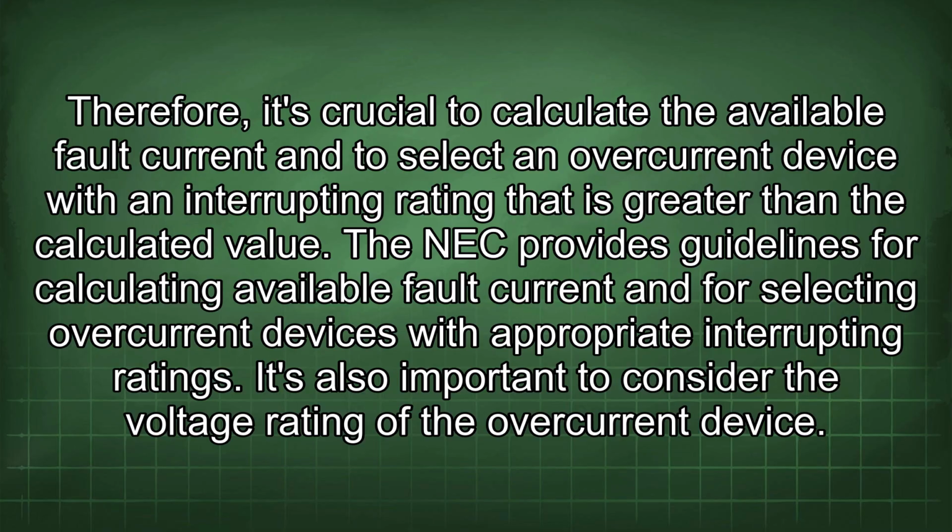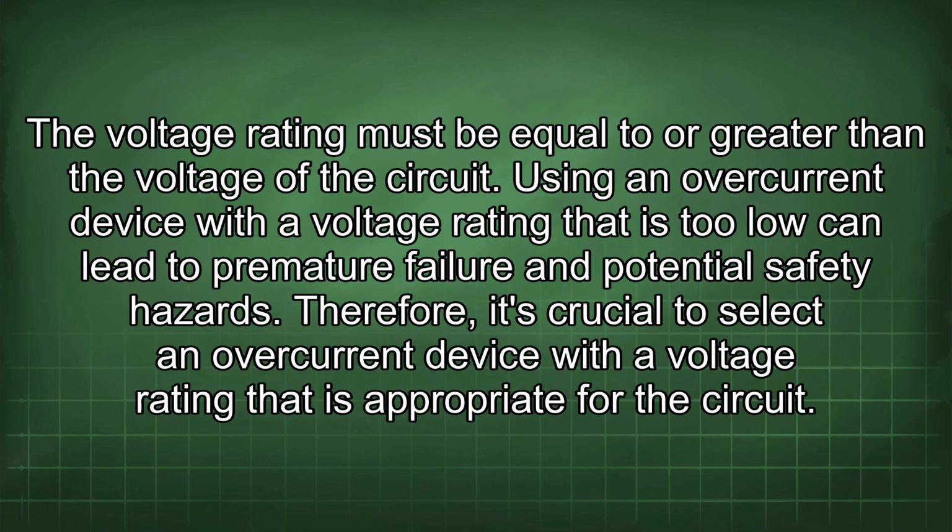It's also important to consider the voltage rating of the overcurrent device. The voltage rating must be equal to or greater than the voltage of the circuit. Using an overcurrent device with a voltage rating that is too low can lead to premature failure and potential safety hazards. Therefore, it's crucial to select an overcurrent device with a voltage rating that is appropriate for the circuit.